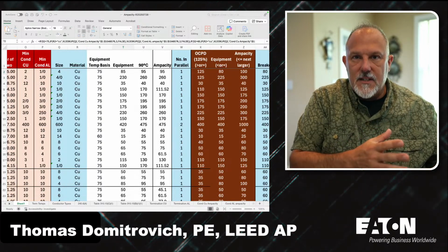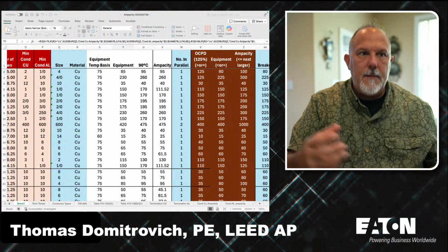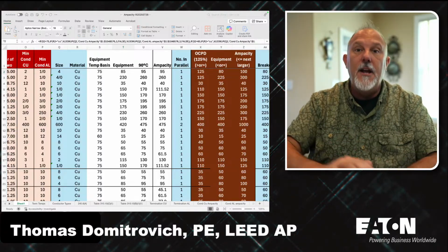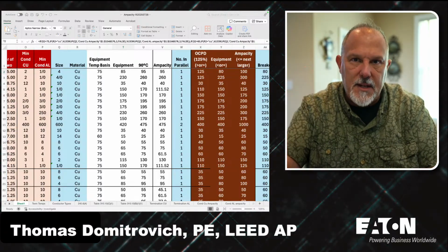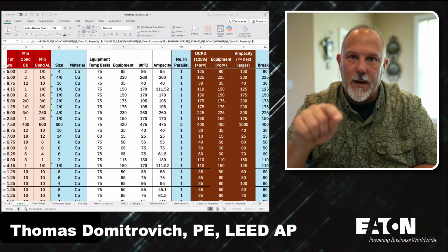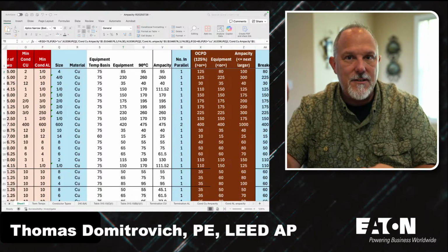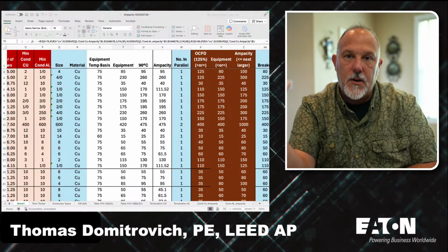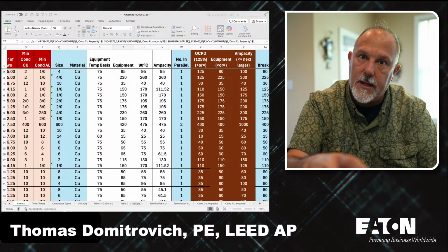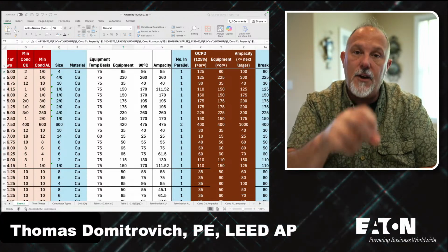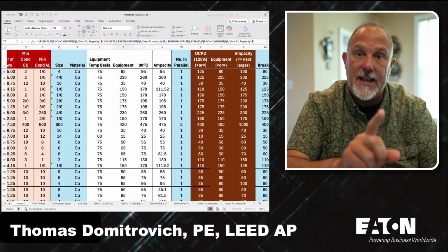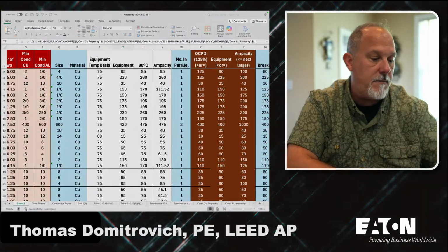But in the UL 67 standard, we have to put that breaker in an assembly. We have to put other devices in there with it. We need to put it in an enclosure. We need to put a dead front on it. And we need to bake it at a certain ambient temperature. And then you need to pass the heat rise test. And that is when things go wrong, because you've put that circuit breaker that you tested in open air as an individual component. Now you've put it into an assembly. And when you put it into an assembly, now you have a different environment for the components, and they will perform differently, especially from a thermal perspective.